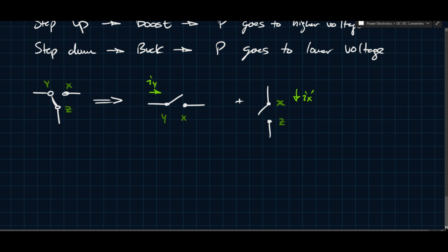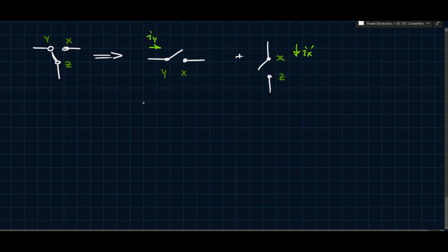And so the way we're going to switch this pair of switches is as follows. If we just look at the voltages, and imagine that this is dt and that this here is T, and we call this Vyx and this Iy, then this will be 0 for this time because this is the series switch, remember, and an on switch has a 0 voltage drop, ideally at least.